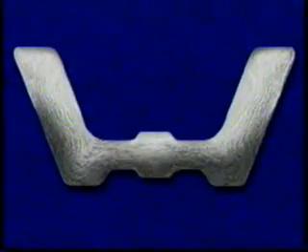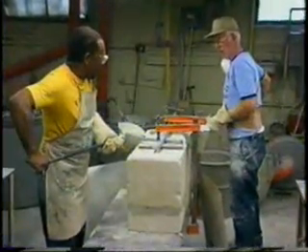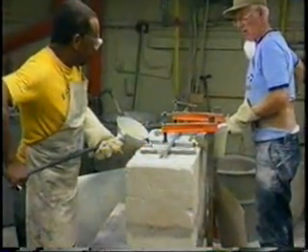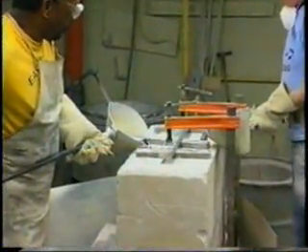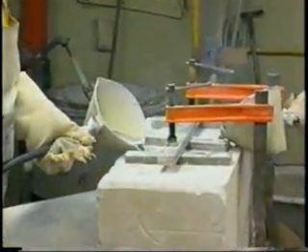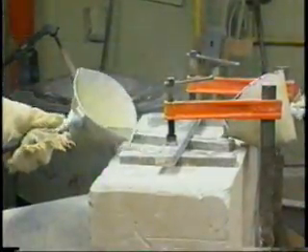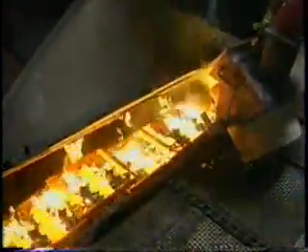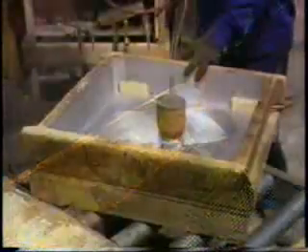Castings typically have an isotropic or uniform grain structure and properties rather than the directional grain structure and properties of wrought metals. Casting is usually the quickest way to shape metal into a part. Because of this, casting is used both for prototyping as well as production of large quantity parts.